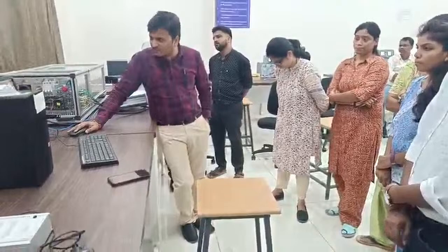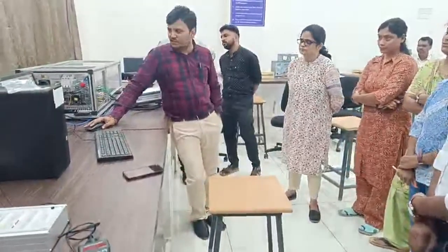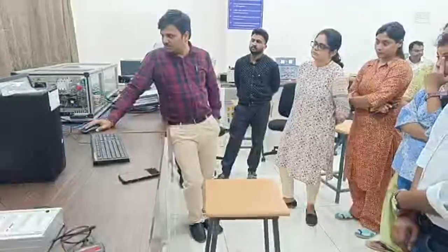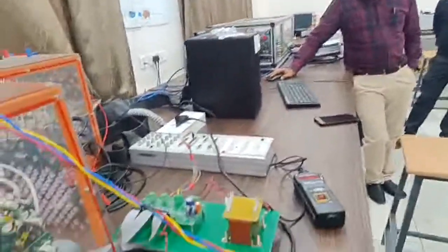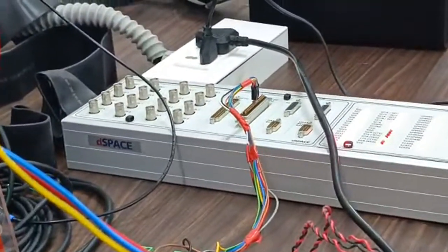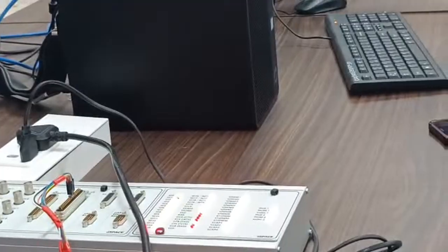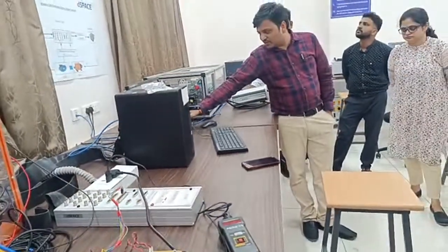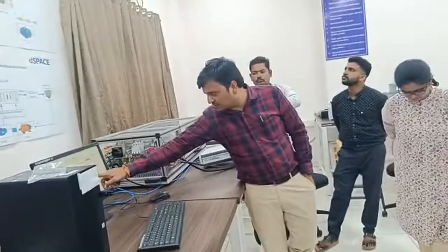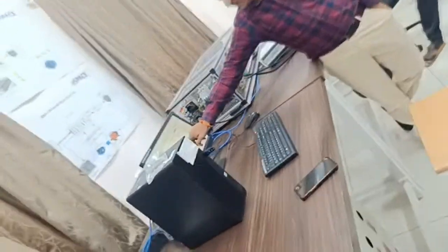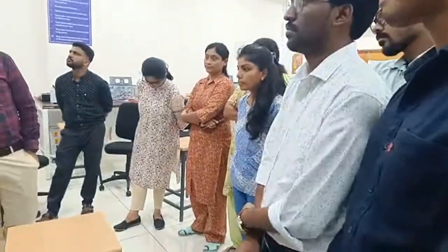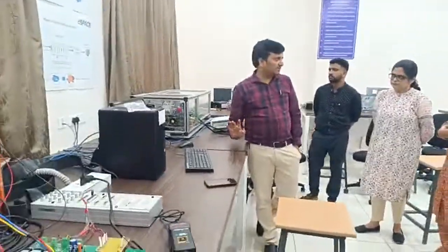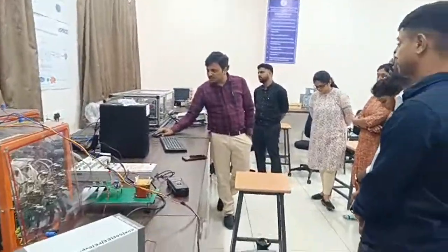This is in the E folder, DS1104 folder. I'll go to the E folder DS1104 folder. You can see the time, 2025 September 23. We ran it at 9:23, and the SDF file is generated. I will select the most recent one. Finish. So the variables are brought here, and this project is connected.